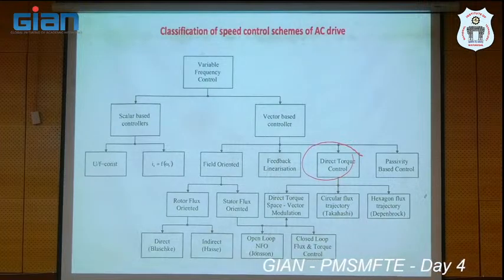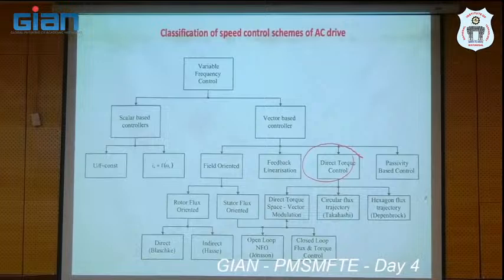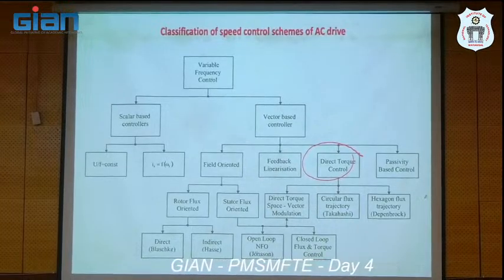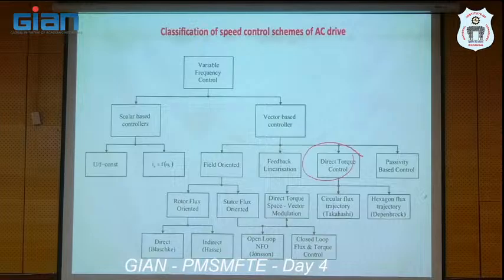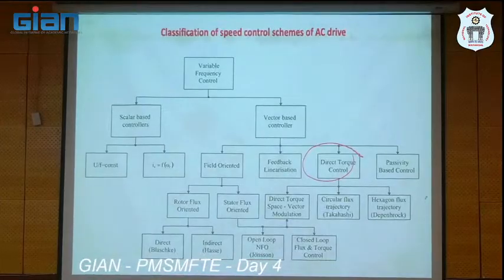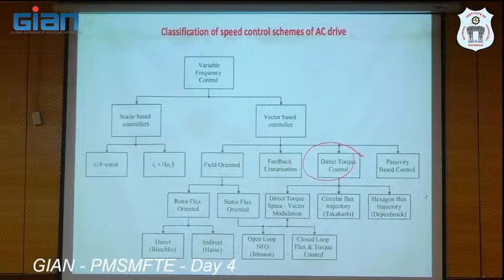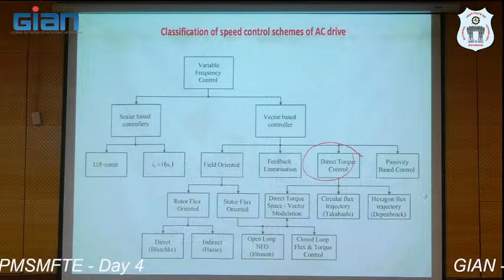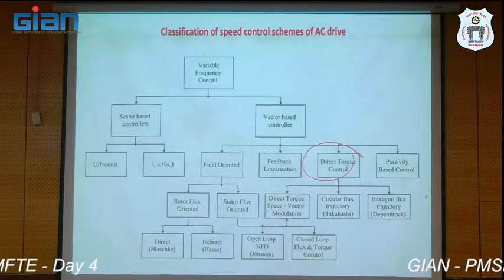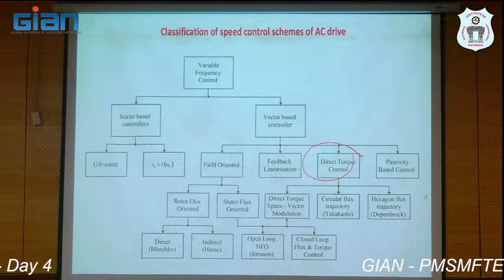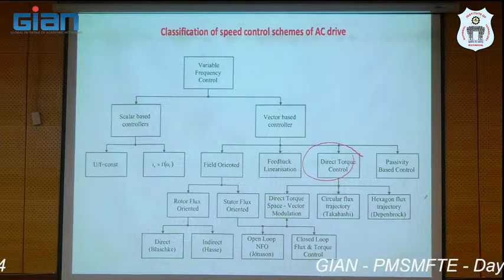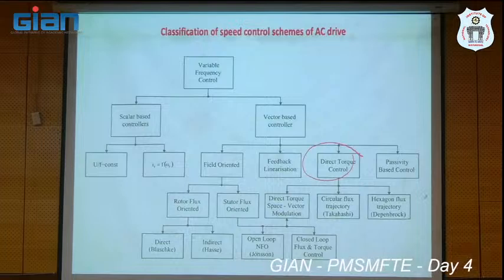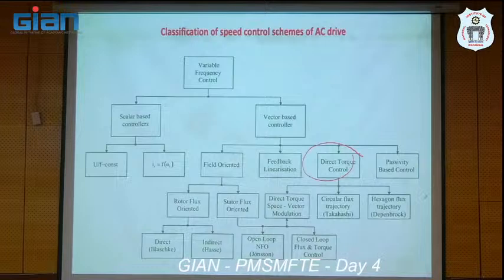But from the drive point of view, if you want to operate for a longer period, because of the heating effect, more period and more load, parameters will definitely be affected. But the advantage of DTC is that it doesn't require the rotor flux position. In DTC, the flux position is required but it need not be that accurate. Even if there is some error, it is fine.